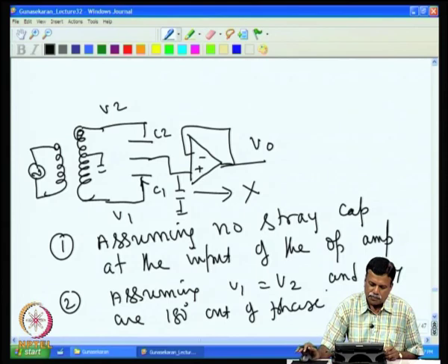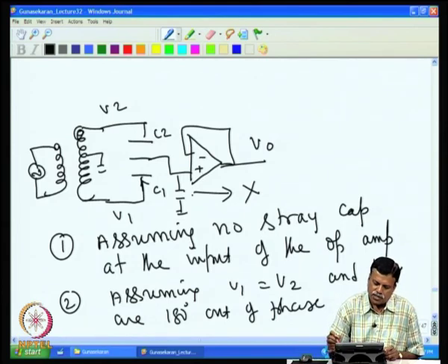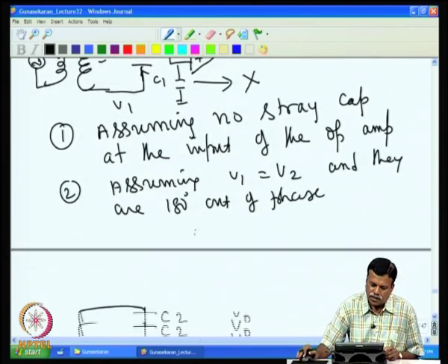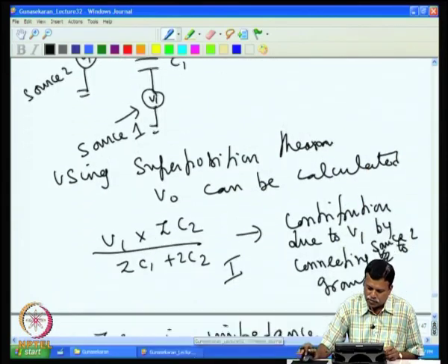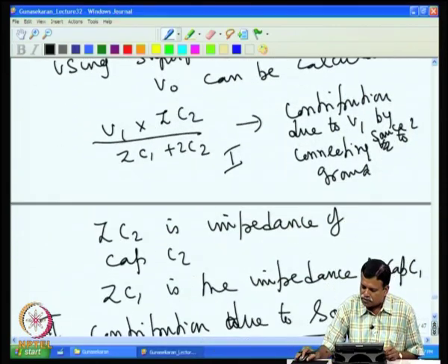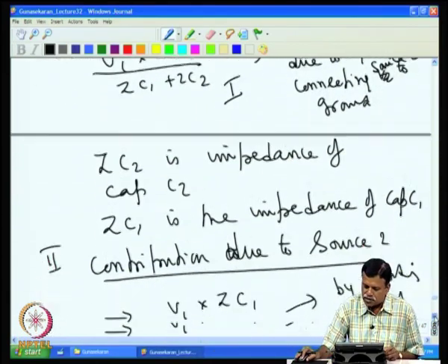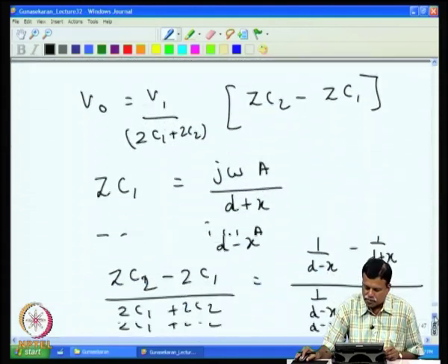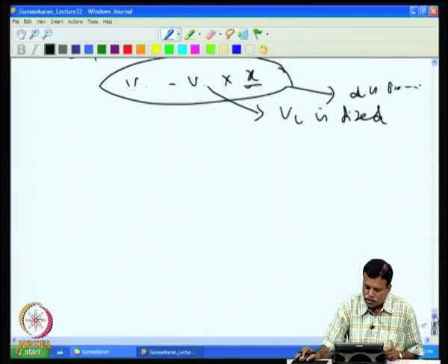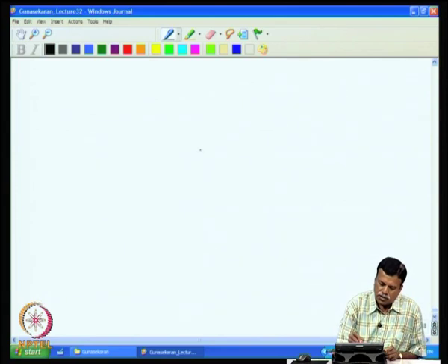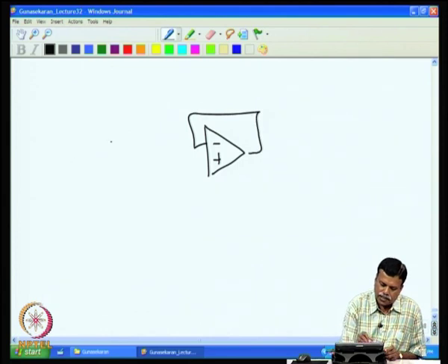Now, the dependence on this capacitance can be solved by guarding the input. So, normally what is done to solve the input impedance stray capacitance problem is that one can guard the input electrodes. So, using the following technique, we can have the input and then the two space variation.